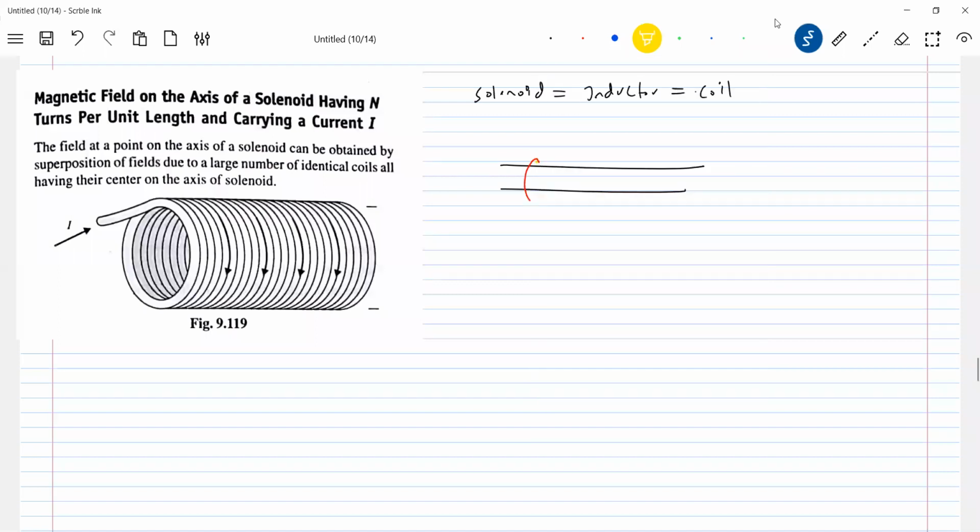Here, I'll have a brush which will be dipped in an insulating liquid. With that brush, what happens? I'll just paste it like this. Then I'll bring another turn. It's a liquid, no? So a very thin layer will be formed on the wire, and the two wires will come in contact. Between the wires, what happens? There will be a thin layer of insulating liquid. I can't bring any solid material. Liquid will be much easier, no?